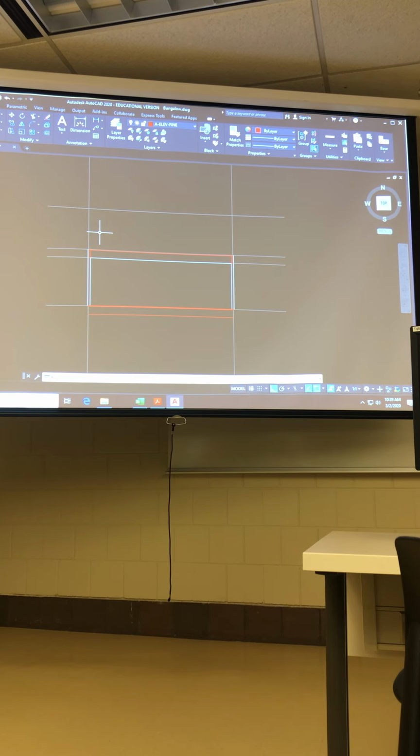at one time. So going back to my packet, I don't really have any helpful information on this section drawing that would tell me where this vertical wall is in the bedroom, or where that web of the truss is, and that's really what I need to figure out next here. So I have to go back to my floor plan drawings and figure out, is there anything there that's gonna help me out?